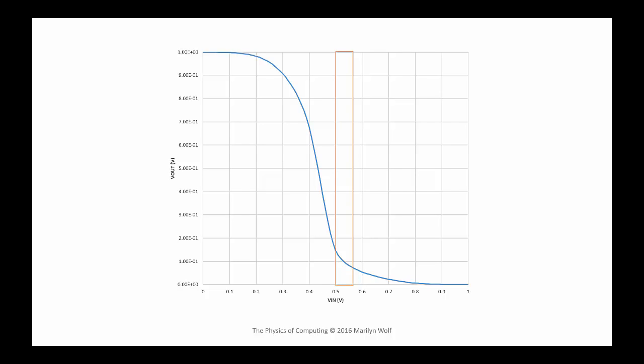We've assumed so far that only one of the transistors is on at a time, but that's not always the case. There is a point during the transition at which both transistors are on. So current can flow from VDD to ground. That's known as a short circuit current. That short circuit current consumes power, but it doesn't help speed up the transition. But if the sum of the magnitudes of the threshold voltages of the pull-up and the pull-down transistor are less than the difference between the power supply and ground, then there is no short circuit current.